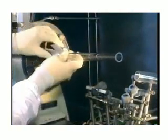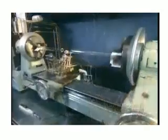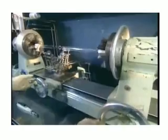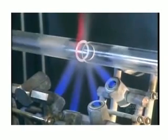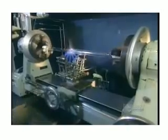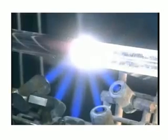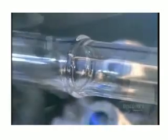Then they set a tube into each end of a lathe. As the tubes spin, they're heated with a hydrogen-oxygen flame. When the glass turns white, it's getting close to peak temperature. At 2,000 degrees Celsius, the two tubes fuse together.